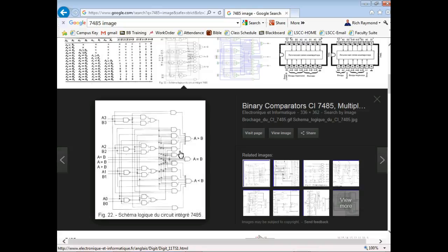What's that? Wire wrapping? Believe me, I've done a lot of wiring. I'll show you all the tools. We have another little technique called split wrap, which is a lot easier. With the wire wrap, you literally have to strip the wire about 1 inch with a little stripper, and then you wrap it on there. Split wrap actually trims the inside for you.